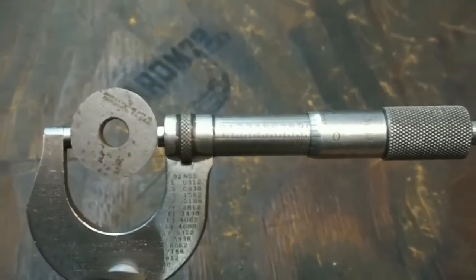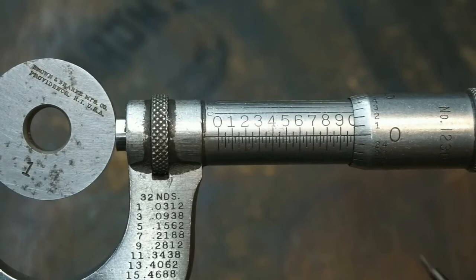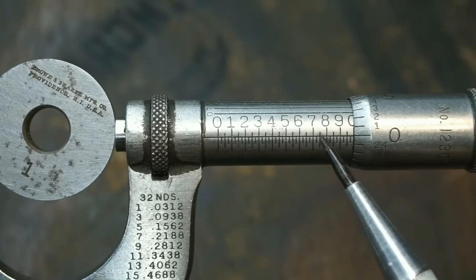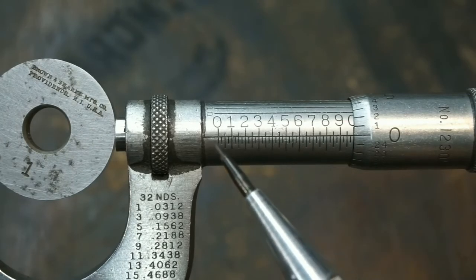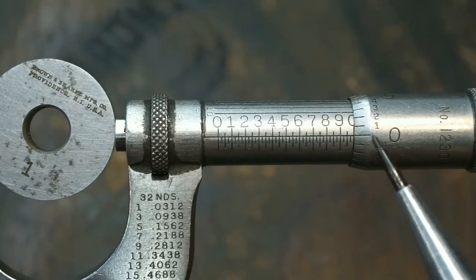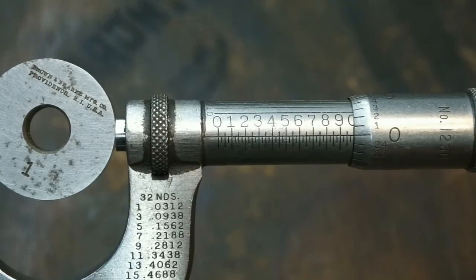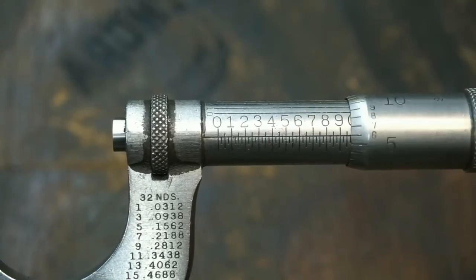And we zoom in there, I think we can see that our 0 point right there is near perfectly lined up with this horizontal line going across there. So that's your reference line on your micrometer in the center there that you're going to be referencing this barrel to right there. So we have a good mic. We're right on size. So we'll go ahead and take that out of there, and we'll go ahead and begin with what all these numbers and lines mean on a micrometer.